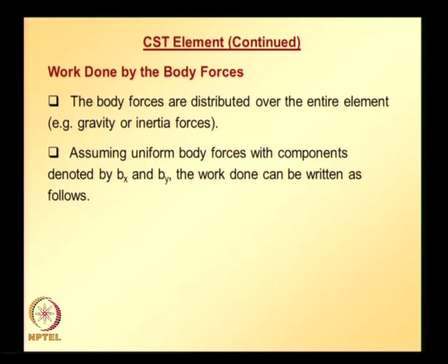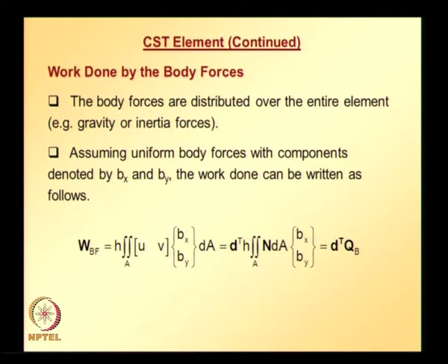Work done due to body forces, that is why it is written as W subscript Bf, Bf stands for body forces, is again the same logic: displacement component times force acting in that direction. Based on that we can calculate work done by the body forces using this formula, or it can be compactly written as W is equal to d transpose QB,